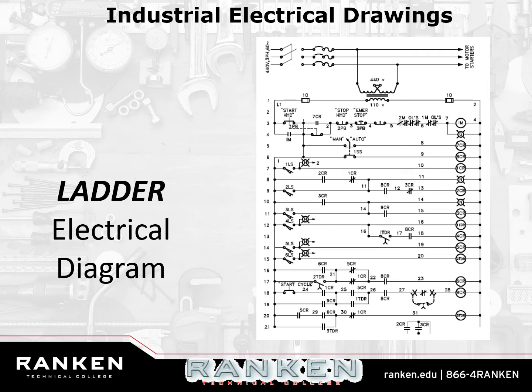Now I got to get number 9CR to close. Number 9CR is all the way down here. This is number 9CR. Well, number 9CR has to close. What has to happen? Well, I have to hit the start button, but also one of these two contacts has to be closed. This contact has to be closed, and these can't be opened. Makes sense, right? Pretty great.